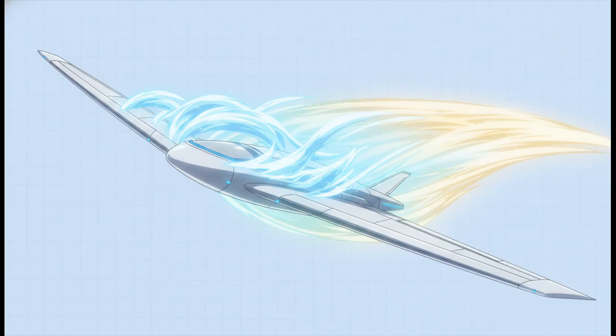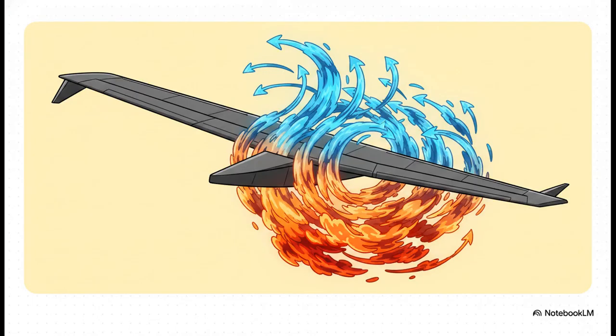That downward-backward downwash from the top surface forces a reaction that results in an upward-forward force on the airfoil itself. To make it super simple, just use this comparison. The low pressure above the wing, which is caused by that fast-moving air, acts almost like a vacuum, naturally pulling the wing up from above.